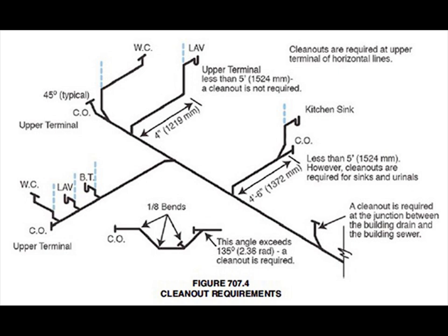It is required on the island kitchen vent because it has a drain on it. It is not required on each lav sink drain since they have accessible traps, but a cleanout is easy to install and surely makes things nice. Cleanouts are required where the pipe leaves the house for the septic. Use a Y branch. Cleanouts are also required at the start of each horizontal main drain run.